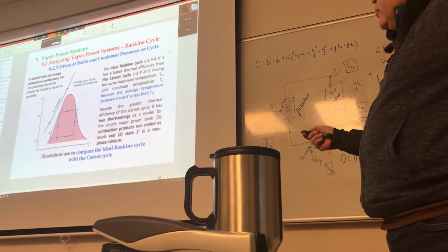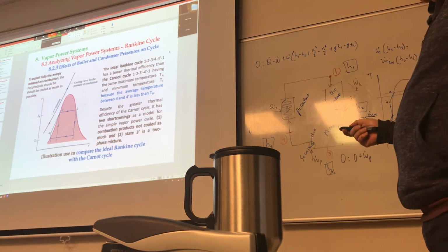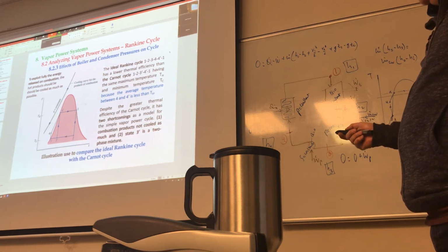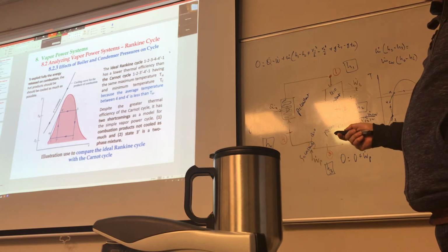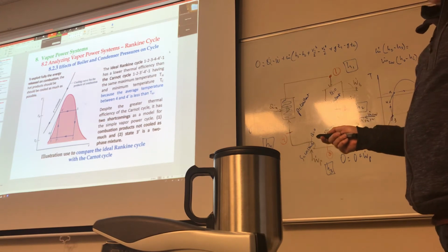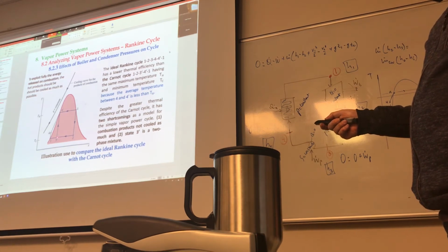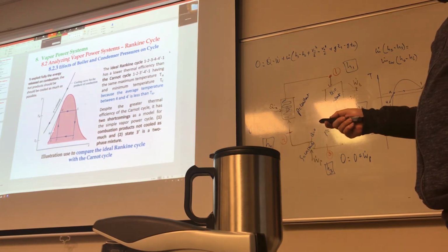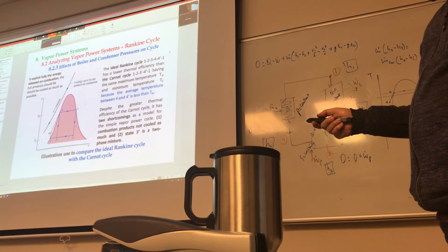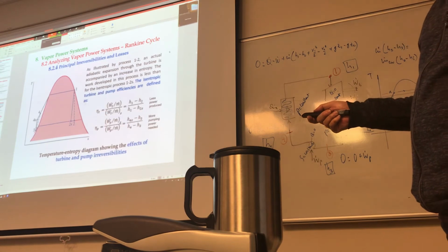It has 2 shortcomings as a model for a simple vapor power cycle. One is combustion products not cooled as much, and state 3 prime is a two-gas, two-phase mixture. Okay, I'm not going to spend too much time on the first one because, well, the next slide actually explains it. The key problem is here, normally you would have a pump in there, right? But here you're pumping vapor and liquid, which is not desired, right? So conceptually it's good, but you cannot make it happen physically.